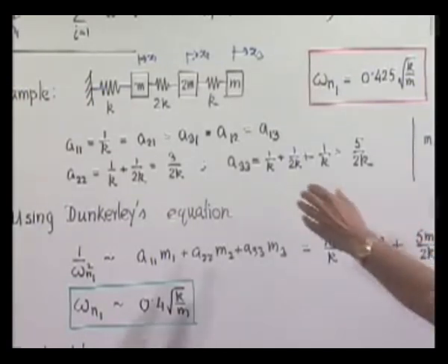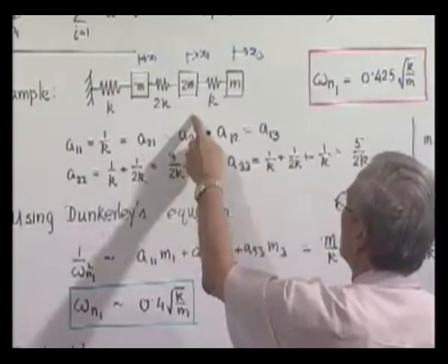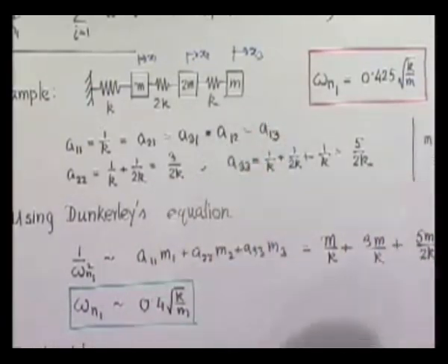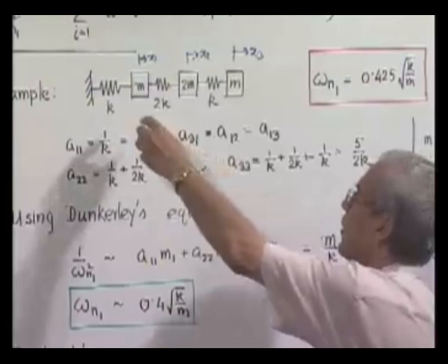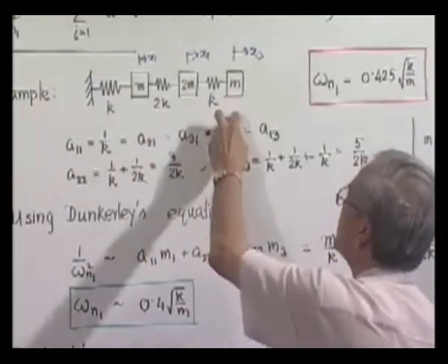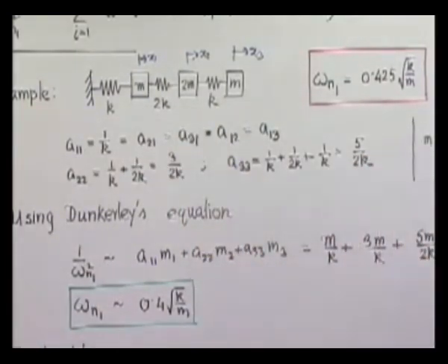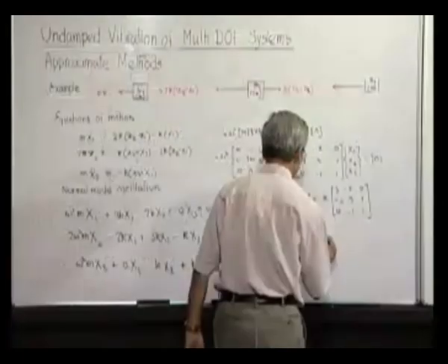So one quick way of having a reasonable assumption is, let us see what is the stretch or displacement at each position due to a gravitational pull. That means if we hang it, what will be the deflection in the static equilibrium position. That is one very common technique used.